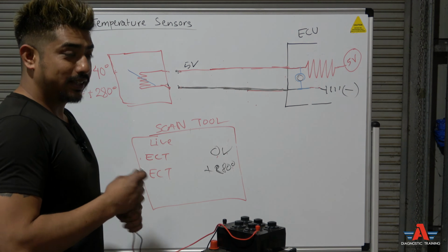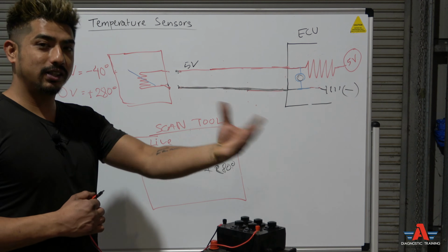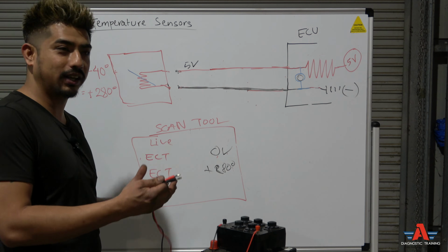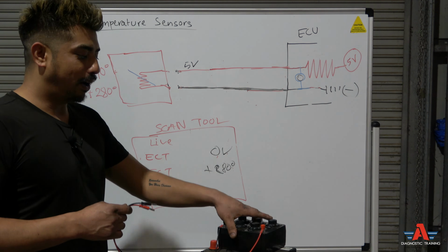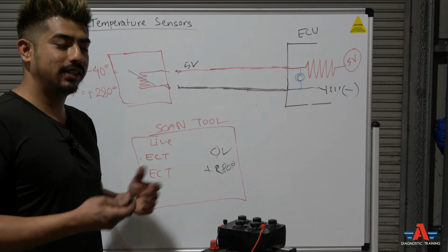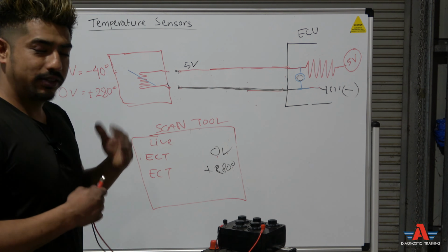Then I started the car, and guess what? It was hunting the whole time. It gave me plenty of time to do my checks and find the reason why it was doing it. At the end, the problem was a vacuum leak in the intake manifold. The rubber gasket on the intake manifold was bad, so it would hunt like that just in the morning.